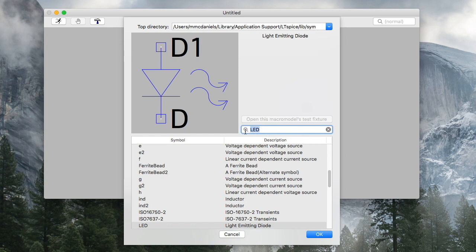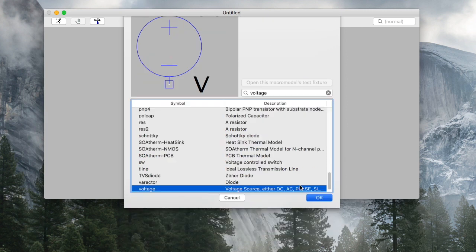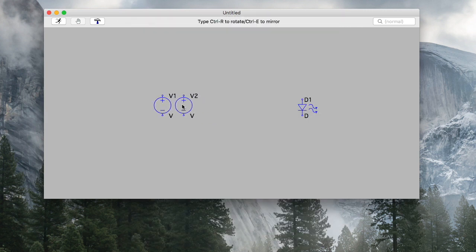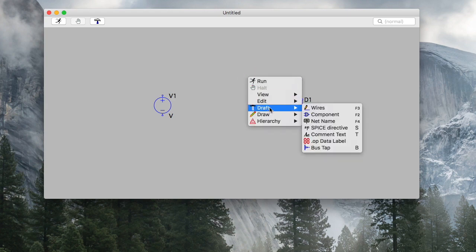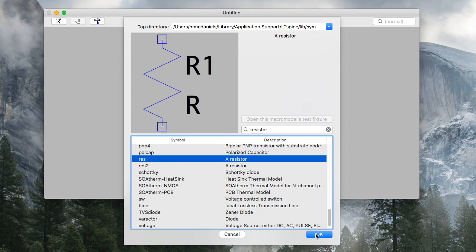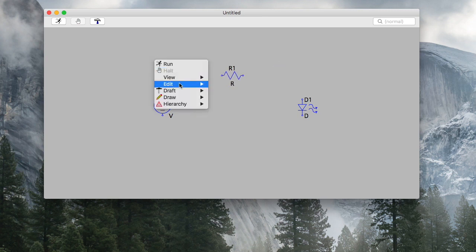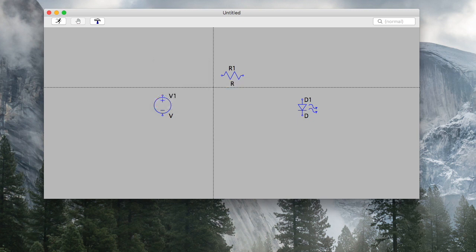the circuit. What that will allow us to do is create a simulation to ramp through resistor values for a 9-volt supply, and produce a graph to determine the optimum current value based on the average forward current of the LED. And once we do that, we can easily follow the curve and see the optimum value at which we want to drive the diode, the LED. Now, the LED we're going to use has an average forward current of 35 milliamps.